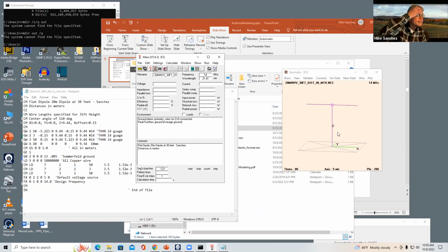Okay, I'm now running it again. Did it come out as a big pole? I got a warning about the wire diameter being more than a third of the wire length or something like that. So if you don't put the millimeter right next to the 10, you might get 10 meters, yeah.